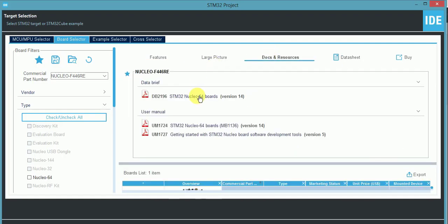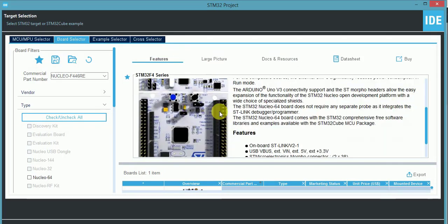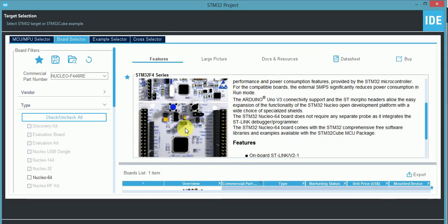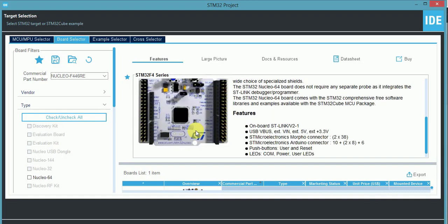There is a user LED over here, right? This is a green color user LED which is present on the board, and over here we have a red color LED that is just a power LED. That power LED shows us whether our board is on or not, that our board is getting sufficient power. We can't use this LED, so we have to use the user LED only. This is the F446RE microchip, the onboard chip. We have to program this chip with the help of the ST-Link circuitry.